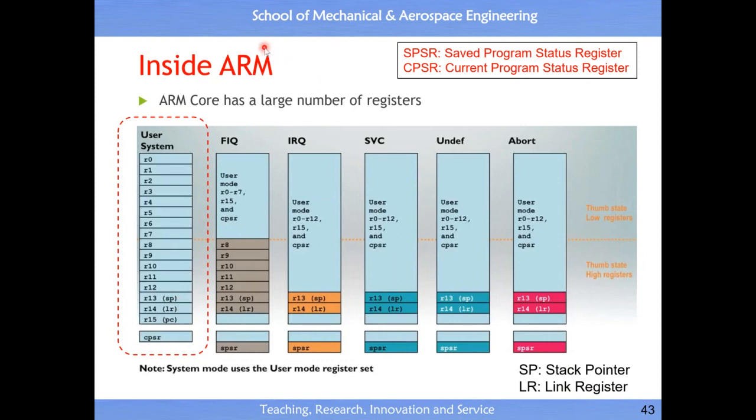For example, when you are inside function 1 and you go to function 2, you must store the status of function 1. And this is the stack register, the stack pointer. That means when we go from one function to another function, the context of the application or computation of function 1 must be stored into the memory.